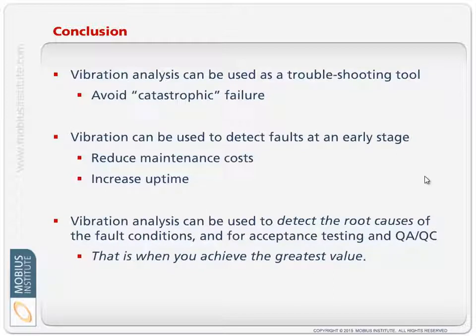All of that is important, but you can do so much more, because if we detect those root causes like unbalance, misalignment, lubrication problems and soft foot and so on, if we detect those early and correct them, then the bearings probably won't fail. And depending on your industry, we might improve quality, we may reduce energy consumption, and all those things if we eliminate those root causes.